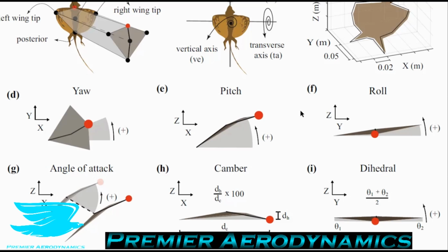So if you think about a regular airplane and you get the wing from the wingtip, and then you pull it up so it rotates about the wing root, if that makes sense. What that does is it increases the angle between the ground and your wing, how it's pointing up. This is called dihedral. And if you push it down, it's called anhedral. Anhedral, A with an A. So dihedral is a very good thing for wings because it increases its stability.